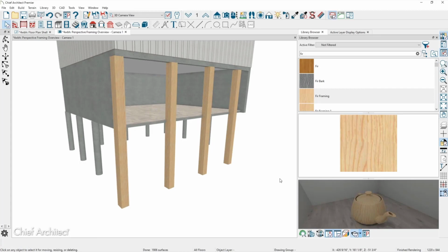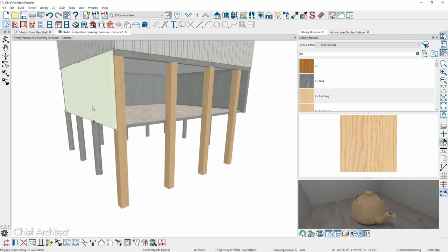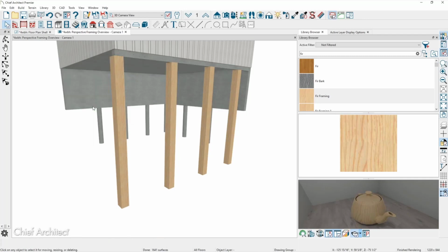Yes. Okay. So now the post and beam thing can give you a start. You can also just manually draw them in yourself. You notice if I delete the wall off to the side, it actually deletes those piers because those are foundation piers. So it might be easier just to draw them in yourself and then dimension them and space them. Get your first one set at the right elevation, and then you can use your copy tool and be pretty specific about it.